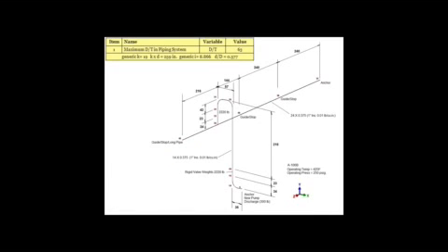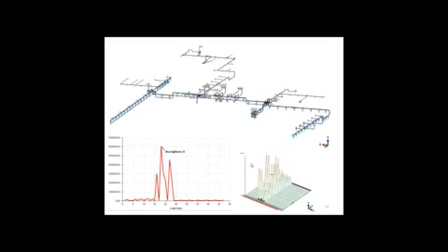If we go to the next model, here's another pump system. This pump system goes up and expands into a branch connection. The piping system from the pump is fairly small. D over T is 63. K times D is 259 inches. When I compare that to the lengths of the piping system, I think I definitely want to run FEA Tools for this system. Another big branch connection, we know what to do here.